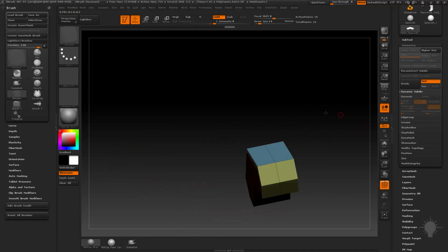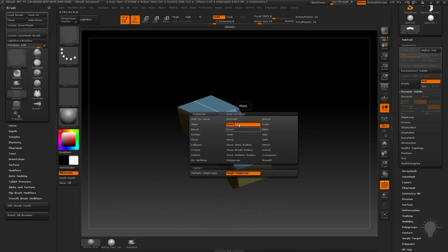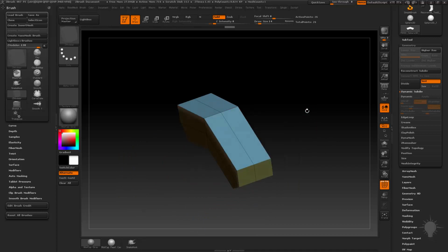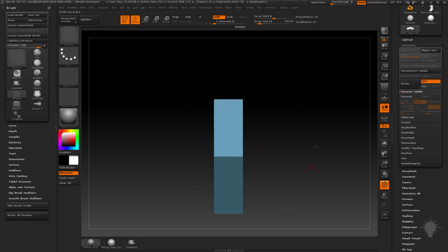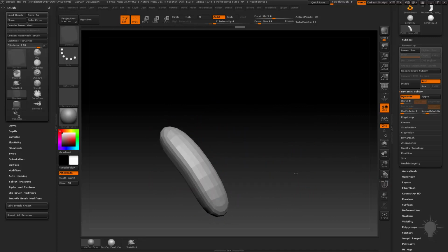If you don't need some of these lines, like I don't need this line down the middle, I'm going to hover over this edge. I'm going to do insert, single edge loop, and instead of just clicking, because that's going to insert an edge loop, I'm going to hold down Alt and tap, and that'll delete that edge loop there. I'll go ahead and keep that one. And I think we've got a good enough stitch to kind of start with.